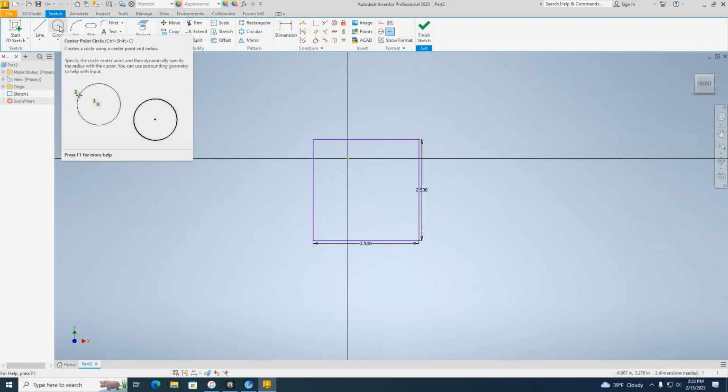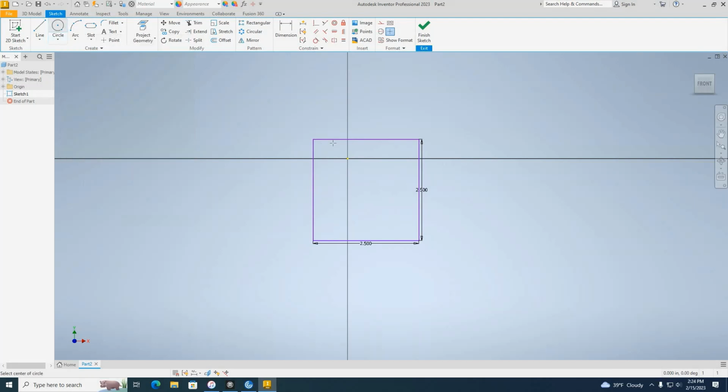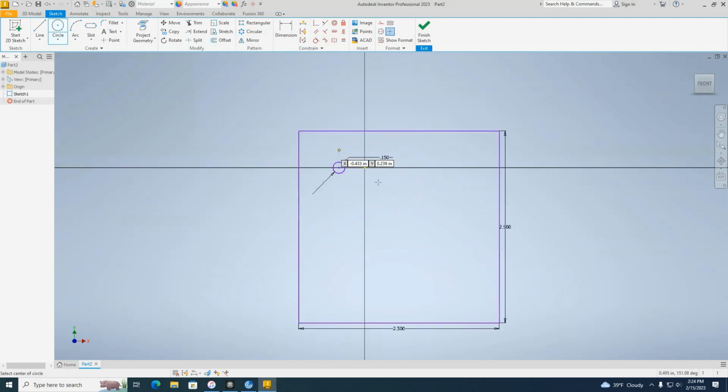So I would suggest just buying a keychain ring on Amazon, and they're all pretty typical, but what I found is taking the circle tool and kind of going up in one corner and typing 0.15. So the dimension on that circle is 0.15, and it fits those standard key rings really well. We also don't want it too far into the key chain or too close. If you get it too close, it could possibly break if there's a twisting action on your key chain.